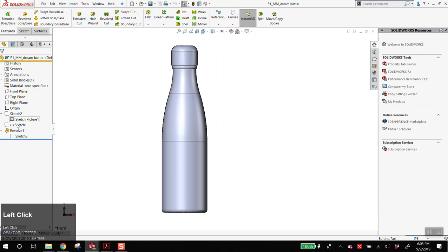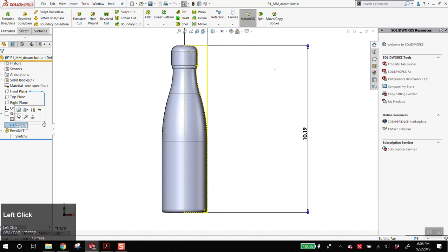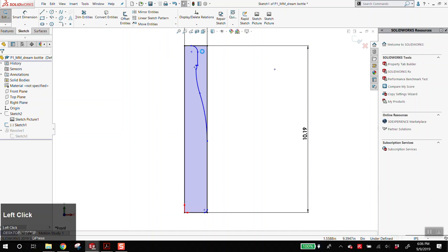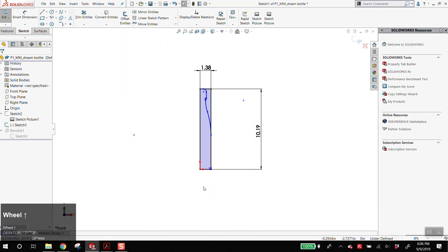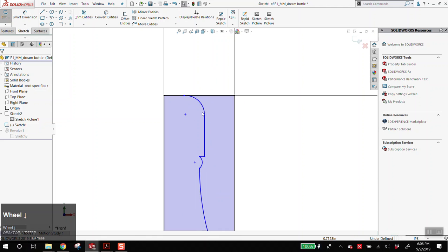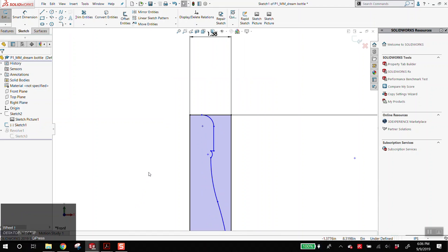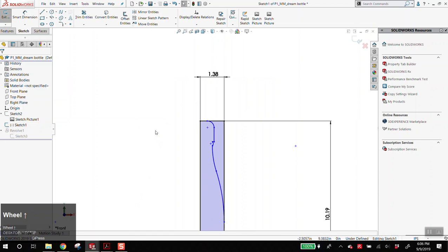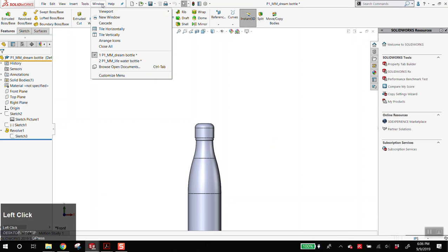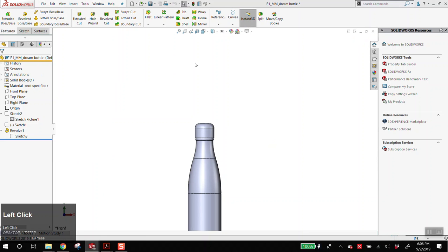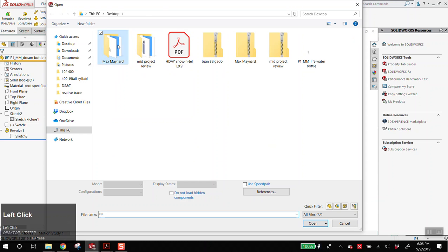So again, this is a good example of reference, master sketch. This is in the right order. You have this correct. Again, it could maybe be a bit more defined, and your origin should be at the bottom. Again, I'll take off points for that. The origin should be here. And then you probably want to define the height of the cap from the origin. Does that make sense? Again, I'll try and look for an option for that. And I'll just look at one last bottle of yours.